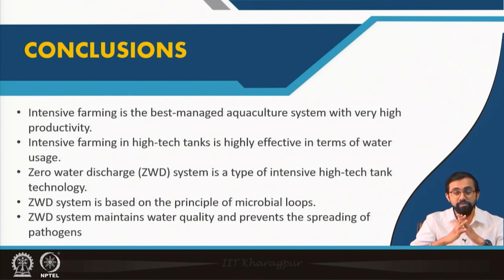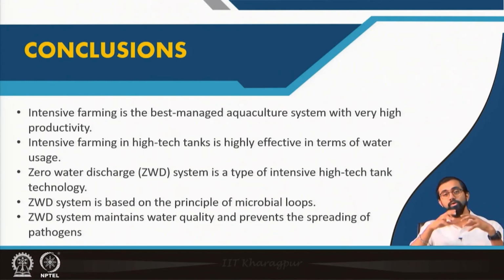Okay, I am giving you one very fine piece of information in this particular case, how the spreading of pathogens is possible to control, possible to prevent. When we go for the heterotrophic growth of microorganisms, which will consume and use this urea and uric acid to convert it to ammonia, we try to go for some friendly heterotrophs like Bacillus. In general, they are the friendly heterotrophic microorganisms, and they have a quorum sensing mechanism by which they can somehow outcompete all the unwanted pathogens present in the system.